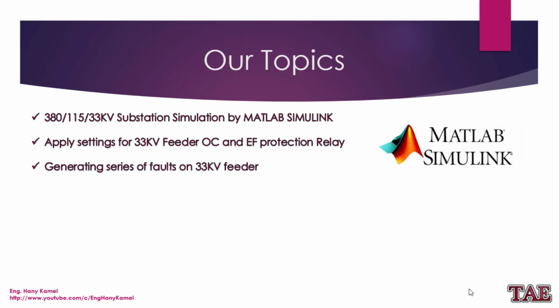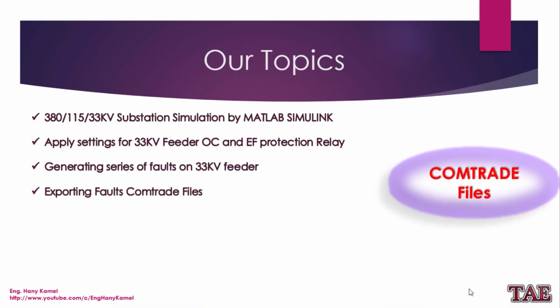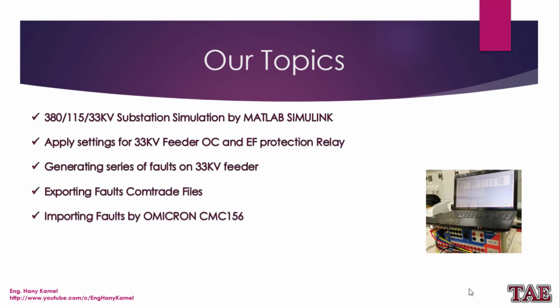We'll generate a series of faults on the 33 kV feeder, which can be expected to happen in real operation. Then we will export the faults to Comtrade files. We will import these faults into the OMICRON CMC156, so we can make re-injection again for protection relay testing.